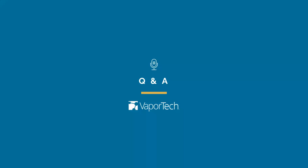If I were to decide in terms of the application itself, if I have concerns about corrosion, I probably would gravitate more towards zirconium based. If it's more about hardness and application in cutting tools, titanium probably is the best choice. So it historically has been used more. Next question. And if I didn't answer that to your satisfaction, you're more than welcome to place the question again or be more specific about what you'd like to hear.